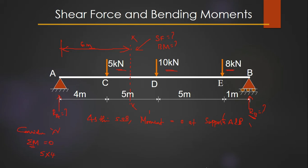Okay, so we have moment due to force 5 kilonewton, and we have moment due to 10 kilonewton, that is 10 into 9, and we have moment due to 8 kilonewton, which is 8 into 14, and we have RB into 15, isn't it? This is equal to 0. The algebraic sum is equal to 0. As you can see here, give the symbols according to their directions.